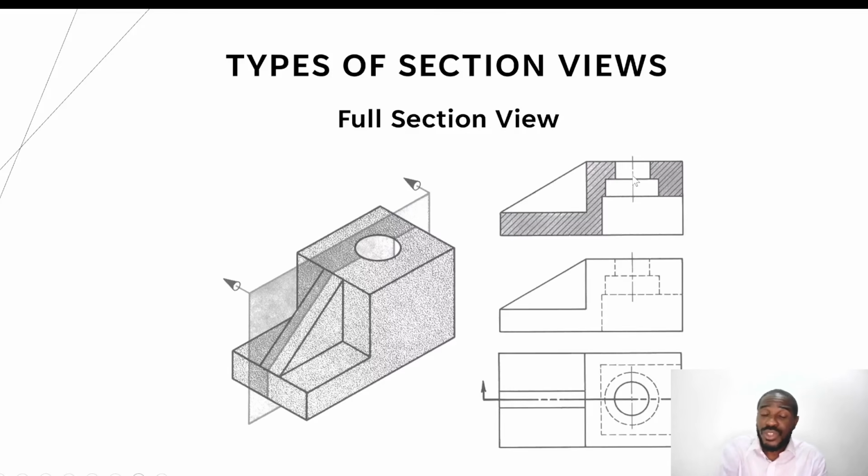That's one of the rules of sectioning, that you do not section even if your plane is going to go through a wedge along its length. It's called the wedge, of course, because it's providing a bridge between this and this, but also you discover that the thickness of it is considerably lesser than the lengths of the sides of the wedge. So if you have a cutting plane that goes through a wedge like this, you do not hatch it.